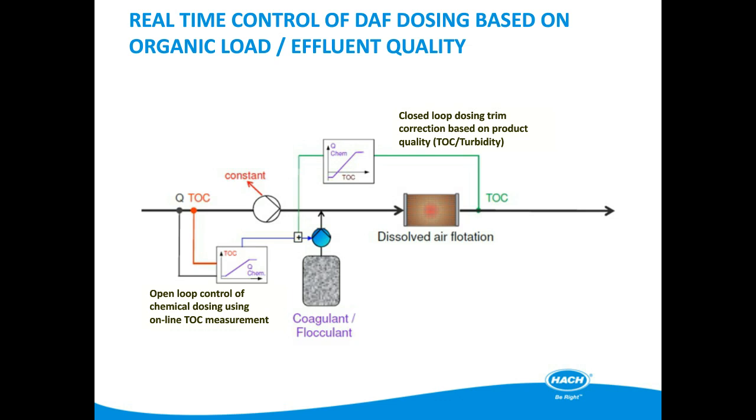I should clarify my previous statement, as originally I did say that the DAF process is a solids removal process, but the flocculation process can also remove dissolved compounds. The flocculant is added in the liquid phase, but transitions into the solid phase. And in the liquid phase, the flocculant can react with other chemical species, forming a solid.